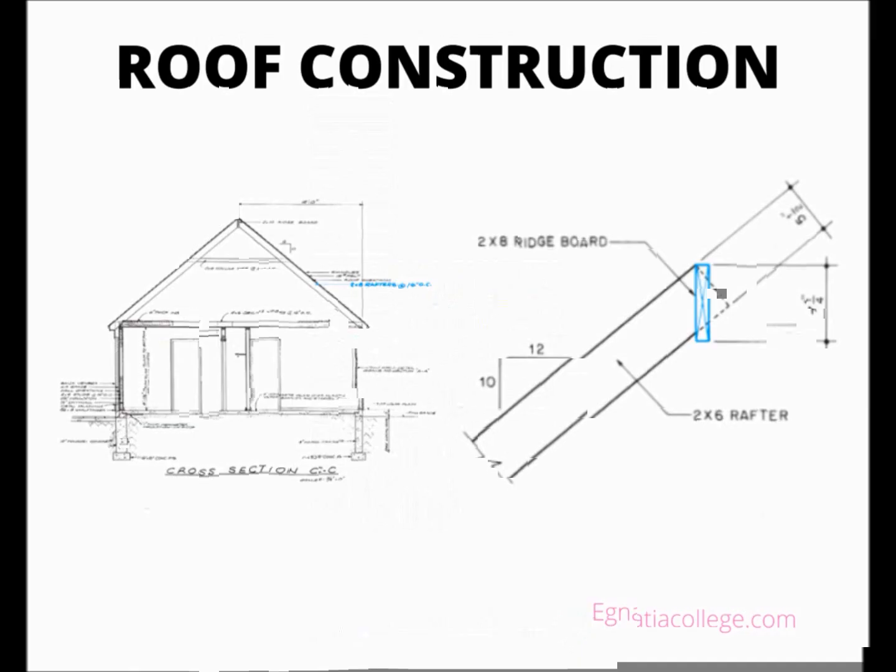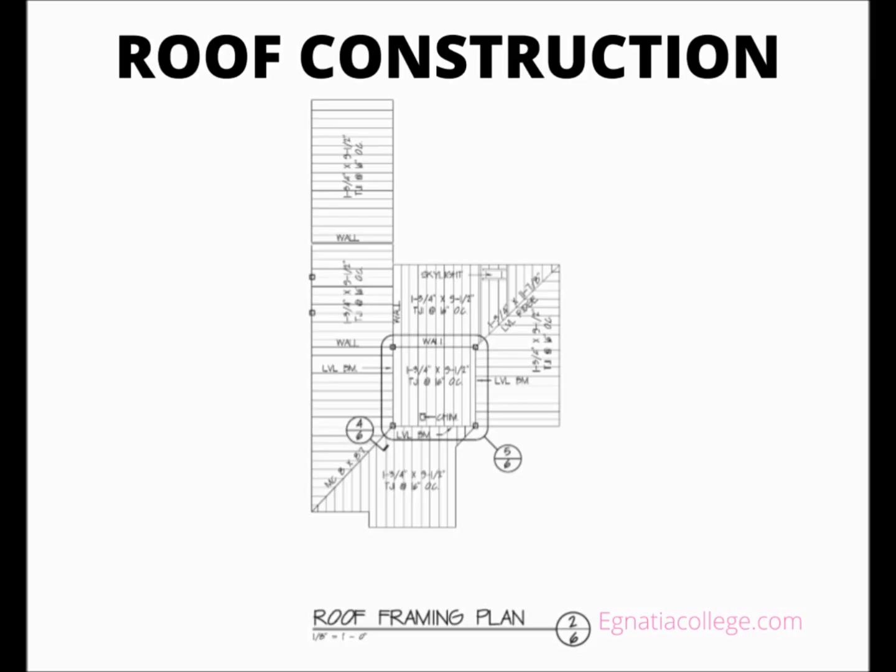Roof framing plans are used only to show the general arrangement of the framing. Therefore, unless specific dimensions are included, framing plans should not be relied upon for the lengths of the framing members.